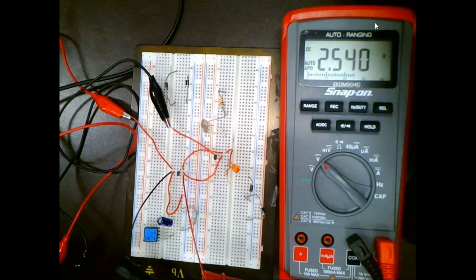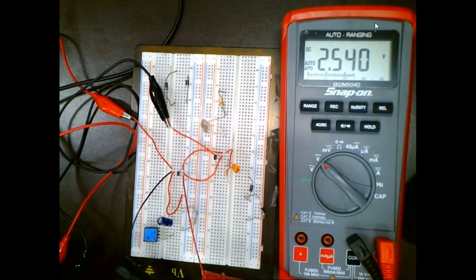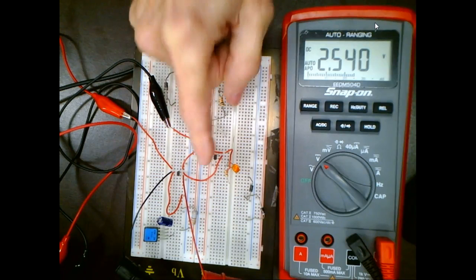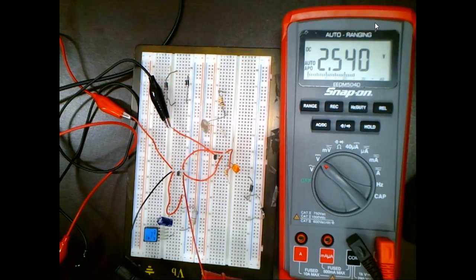Anytime they say switch, limit switch, photoelectric switch, then these are digital devices. You understand that? So we okay with that? Pretty sweet. Look at the size of these things. Now they can't conduct a lot of current, but the PLC only requires a few milliamps to trip the input. So these guys would work great inputting into a PLC, but we wouldn't let it run much.